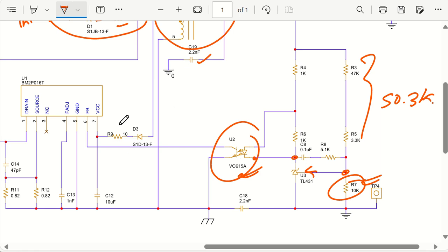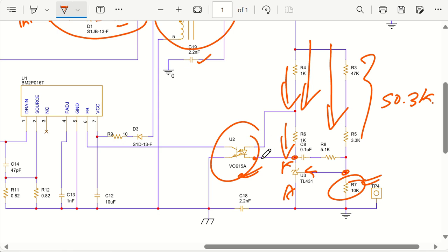Okay. Now slowly we are moving to the controller IC place. So this was the feedback part, and this is the fast lane. The fast lane makes sure that the current flowing through this particular IC will be how much? 15 by 1 kilo ohm. So basically it makes sure that the current flowing from cathode to anode is around 1 milliamperes. Let's say the voltage drop across this particular diode is 1 volt. So 1 volt by 1 kilo ohm will be 1 milliamps flowing through this. And this is the RC circuit that is introduced to have extra poles and zeros.